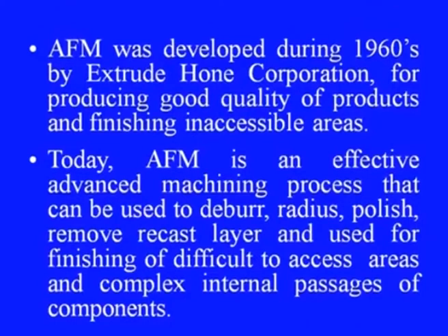Today, this process, abrasive flow machining, is an effective advanced machining process that can be used to deburr, radius, polish, remove recast layers, and also can be used for finishing difficult to access areas and complex internal passages of components, which I have just now discussed.